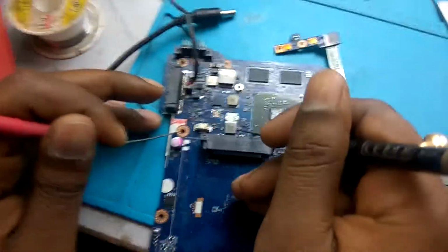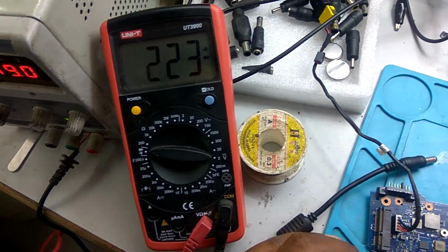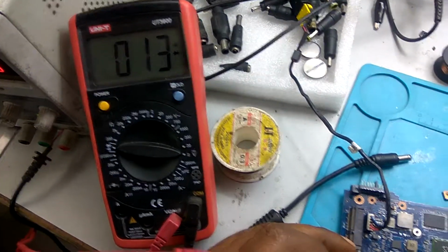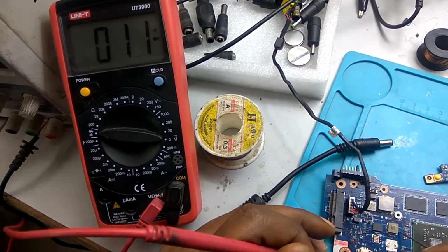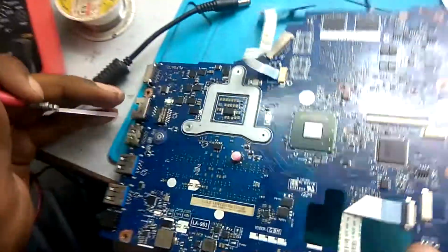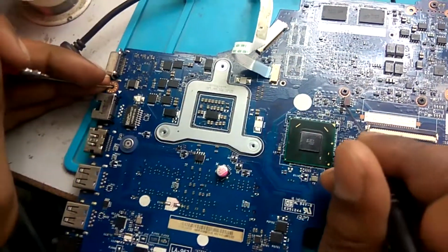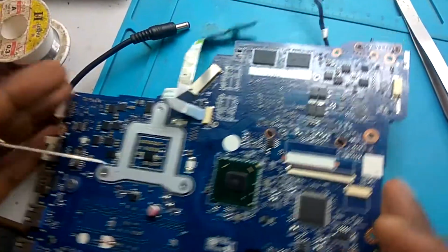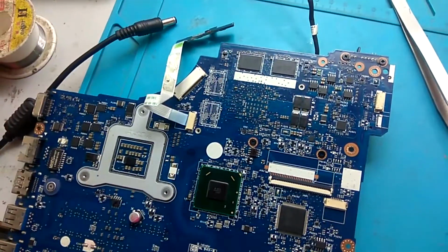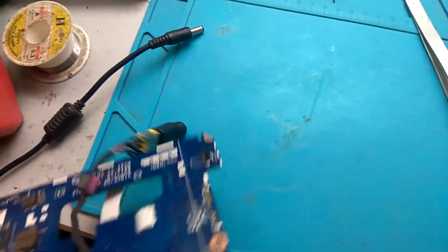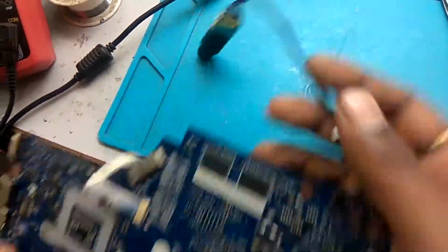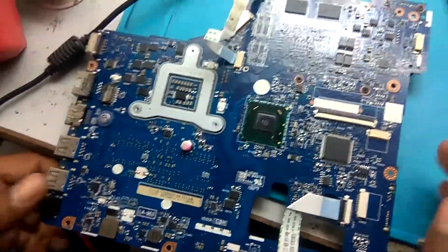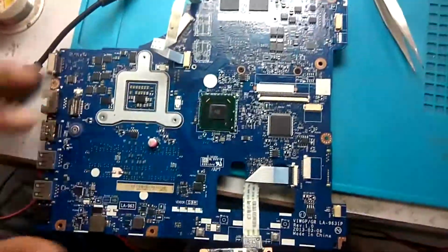Okay, 0.9. But in this part you can see here it's showing short. Okay, means some part of this graphic chip is faulty. This graphic chip is not fully faulty, some part is faulty, that's why it's showing 0. Okay, for this type what we have to do,